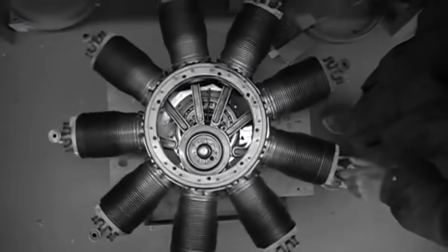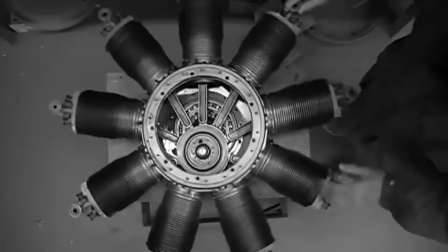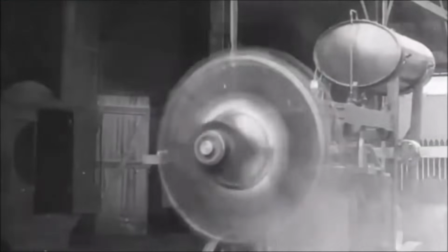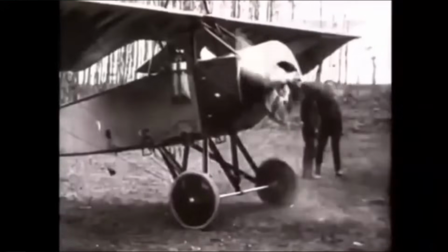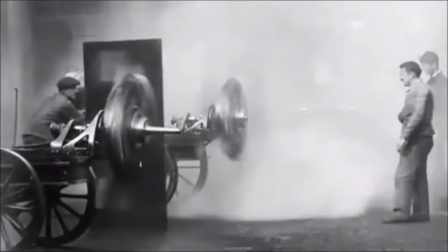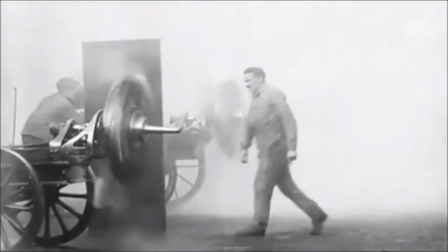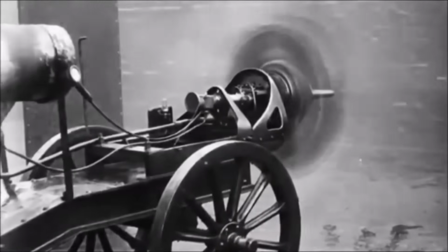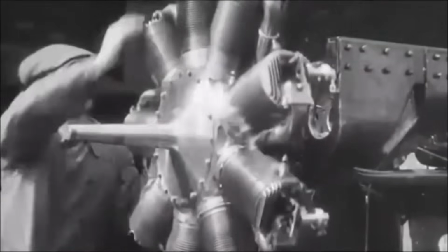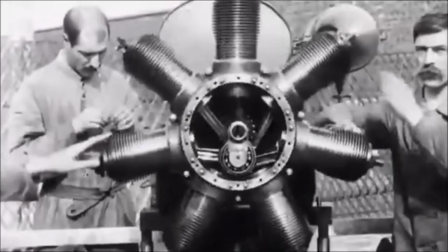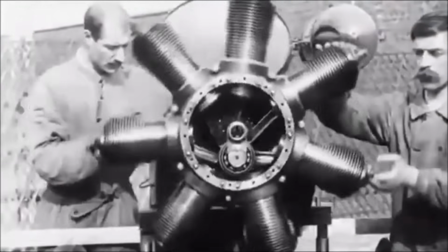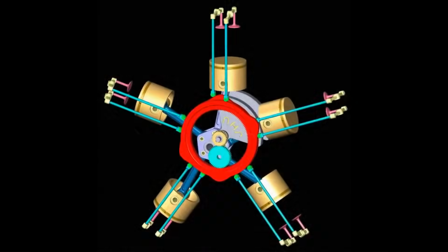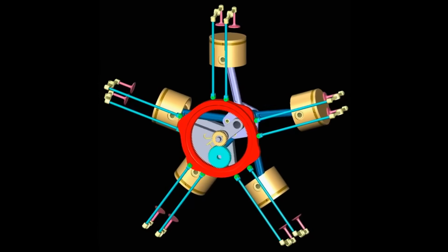However, no matter how difficult the first steps were, the rotary engine continued to develop and later became widely used on airplanes in the 1910s and, in particular, during World War I. Companies like Gnome, Le Rhône, Clerget, Bentley, and others produced these engines. However, due to a number of drawbacks that I have already mentioned earlier, the main ones being limitations in size and rotational speed because of the strength limit of the crankcase and the limit on the amount of fuel-air mixture that can be drawn in through the hollow crankshaft, rotary engines gave way to radial engines with stationary cylinders and a rotating crankshaft.